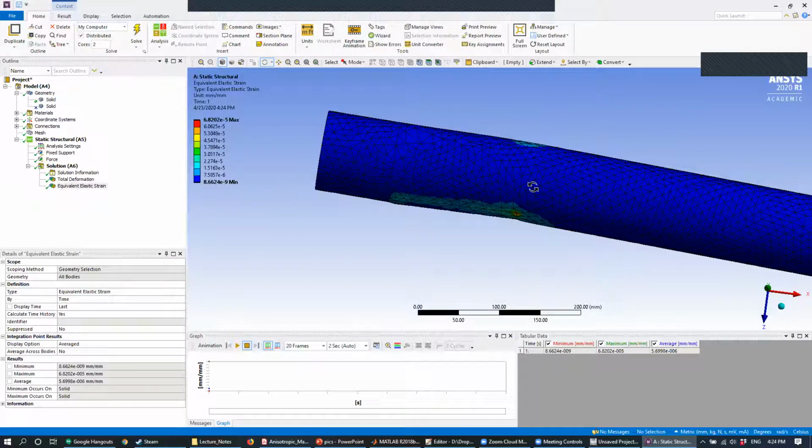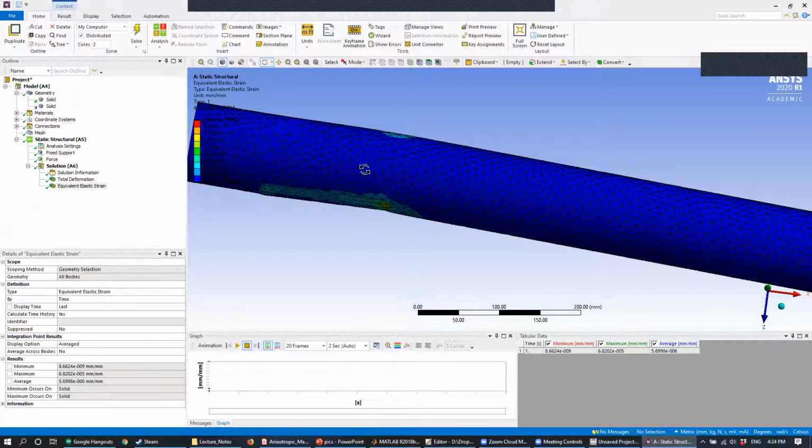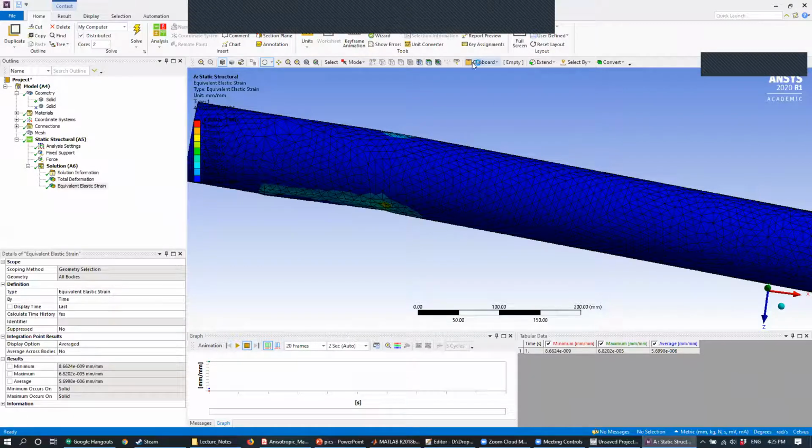So that's basically it for adding phantom surfaces. This was a fairly basic example, but hopefully you can use this and twist it into something useful for your project, especially since I think a lot of you have interesting areas of force application, where you have a certain object or a person standing on top of your object. So you can use this tool to trace out the exact areas where that force is going to be applied, instead of awkwardly applying it over the entire surface of your model. Okay. Any final questions on this?